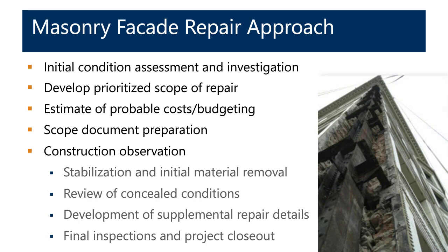And really one of the incredibly important steps in this approach is the construction observation, which oftentimes has some stabilization and additional material removal happening, really understanding what the concealed conditions are, what we cannot see until we get up and start to take the building apart. Oftentimes this results in development of supplemental repair details, and then ultimately final inspections and project closeout.